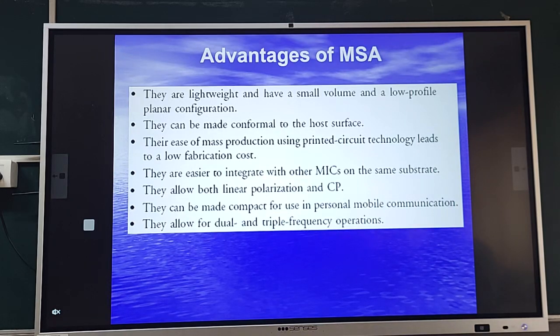So when the signal undergoes these multiple paths, there are bound to be changes in the polarization of the incoming wave. If that happens and I have a fixed polarization antenna at the receiver, I may come across signal loss. Just imagine a very practical example: you keep your mobile phone randomly in any orientation, vertical or horizontal, in your pocket, on your desk or wherever.